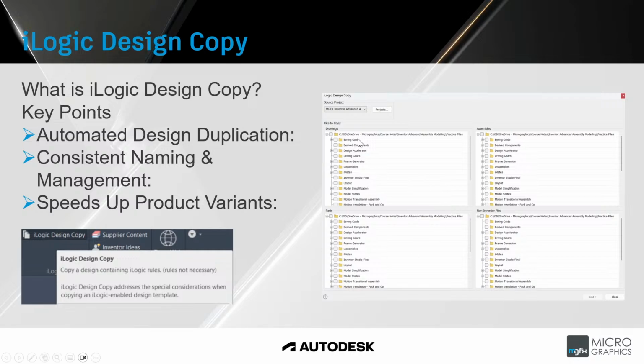As you can see, here's an example of an iLogic Design Copy where you can choose the project you're going to copy it from. You can choose your drawings, parts, non-Inventor files, assemblies, and then you can copy it into a new product or project.